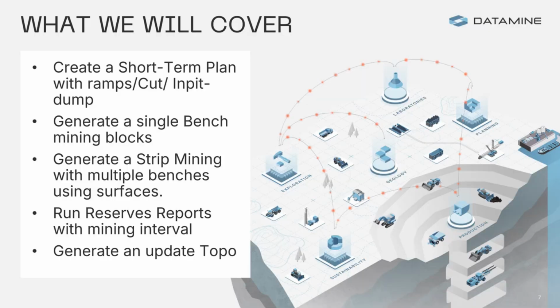And today's webinar, as I've mentioned, is creating a short-term plan with mining blocks. What we're going to cover is creating a short-term plan with cards, ramps, and also the input dumps. We'll be able to generate mining blocks for a single bench, be it a truck and shovel bench, and we'll be able to generate strip mining with multiple benches using different surfaces.